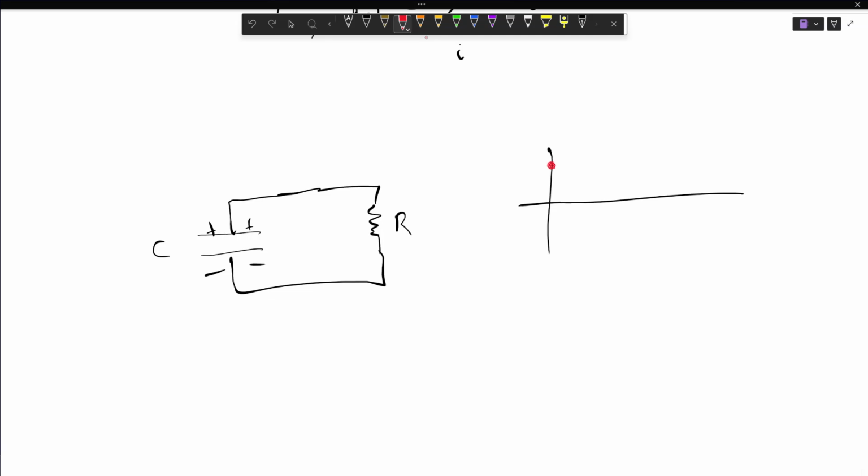the voltage across this capacitor starts high, but eventually it gets to 0. And it does this, as we'll find when we solve that differential equation, in this exponential decay. This is, again, if we're graphing that capacitor voltage as a function of time. And it turns out that essentially every quantity has these relationships that look like some sort of exponential decay with some sort of initial condition, and some sort of asymptote. But they're not all the same.